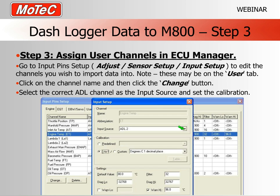We'll explain this a little bit later, but normally, of course, if you have for example a temperature sensor going into an input pin, what it produces is a range of voltages, and then the ECU Manager has a predefined table which matches that particular sensor. However, what we're receiving is actually CAN data, and so it comes in simply as a number on the CAN bus, and then we have to assign how that number is translated, you might say. So what I've got here, it's set to 1:1, and then it's also got degrees, 1 decimal place.